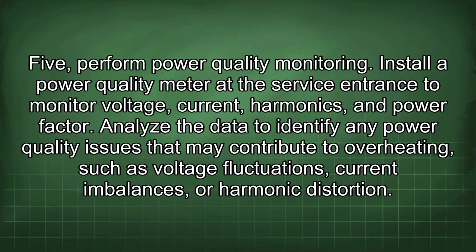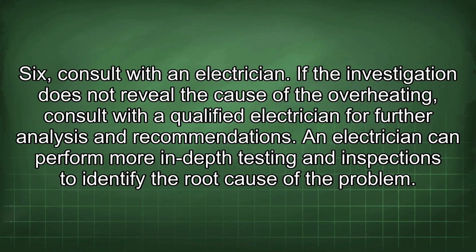5. Perform power quality monitoring. Install a power quality meter at the service entrance to monitor voltage, current, harmonics, and power factor. Analyze the data to identify any power quality issues that may contribute to overheating, such as voltage fluctuations, current imbalances, or harmonic distortion. 6. Consult with an electrician. If the investigation does not reveal the cause of the overheating, consult with a qualified electrician for further analysis and recommendations. An electrician can perform more in-depth testing and inspections to identify the root cause of the problem.